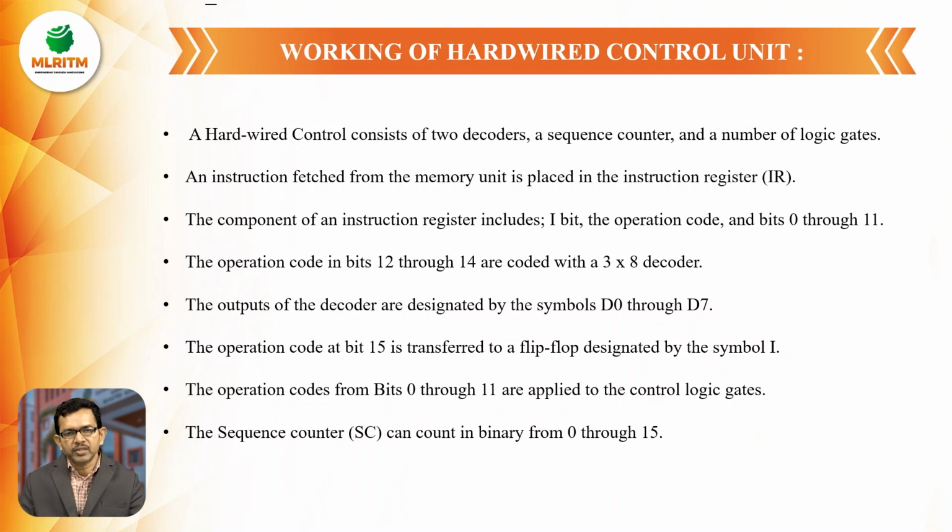The 0 to 11 bits are occupied by the address and the data. The next 3 bits are stored for the opcode. The opcode gives which operation is to be performed on the register data. Suppose I am going to send some n number of bits into the instruction register; these instruction registers should have some operation, and that operation is carried out by the opcode.